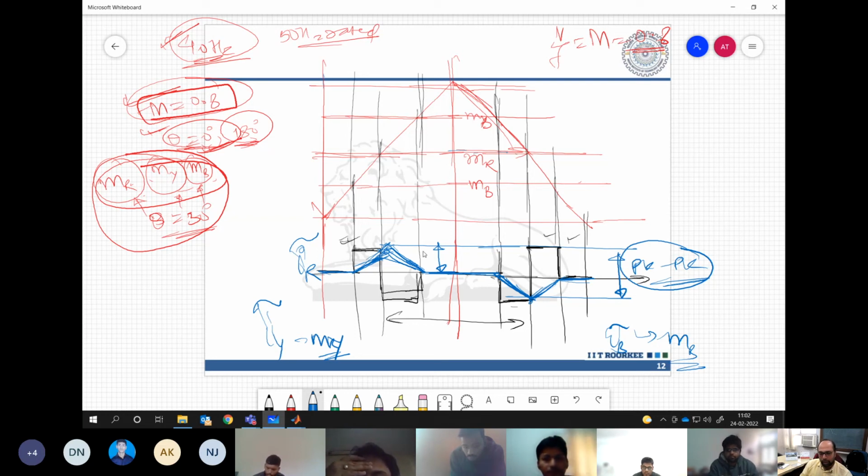Any other value of MR if you take, you see that these values are changing within this subcycle itself. It is going negative, then positive, then again coming back to 0. So it's having multiple transitions across 0. That's why the amplitude comes down. Here it is freely going to one very high value and coming back to 0. So which is why we see the worst ripple coming at the 0 crossing.